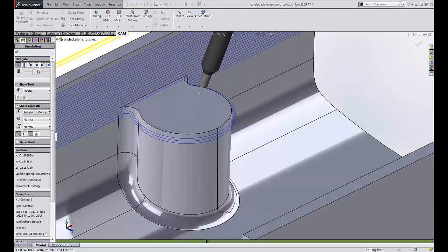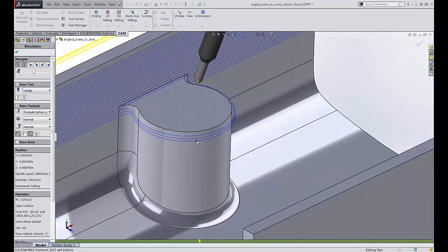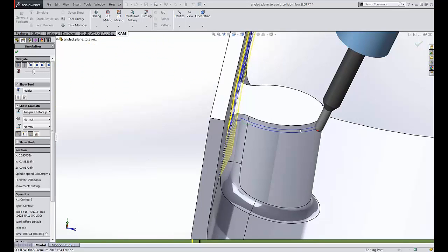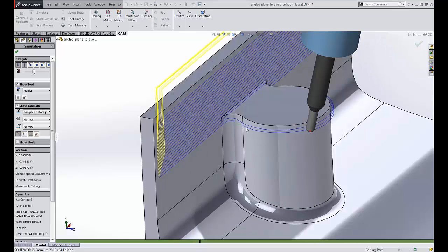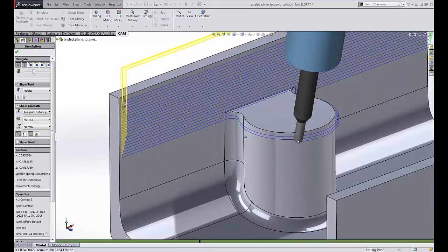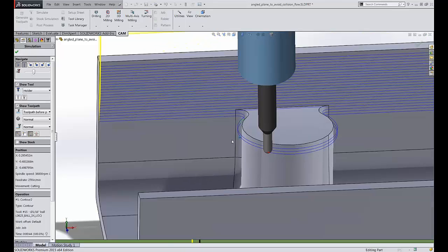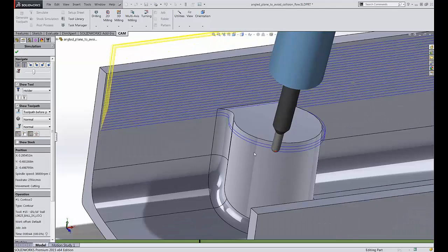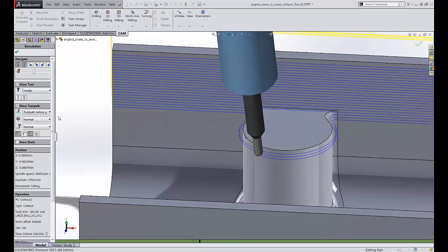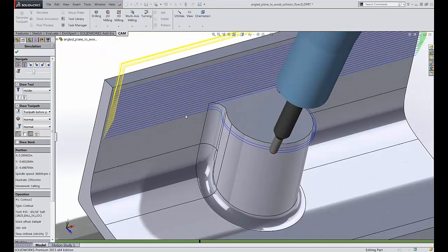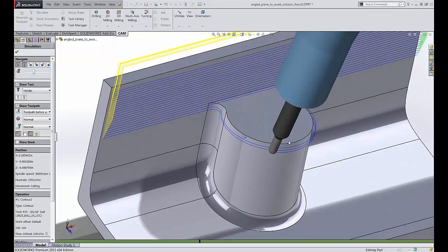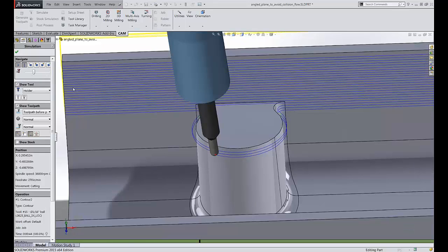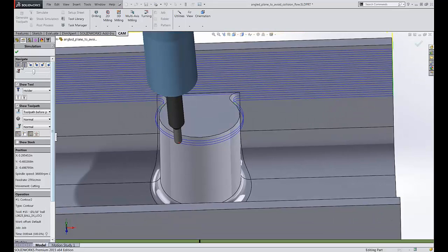It's maintaining, even though there's no risk of the shank colliding here, that tilt to provide you with a nice smooth toolpath. What you wouldn't want to have happen is it just adds extraneous motion here to correct the tilt and then tilts back when it gets done. So I think the logic here is that it goes along, finds a solution, and maintains that solution until that solution doesn't work anymore.